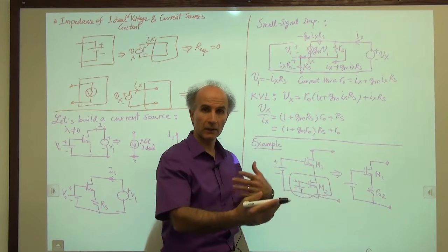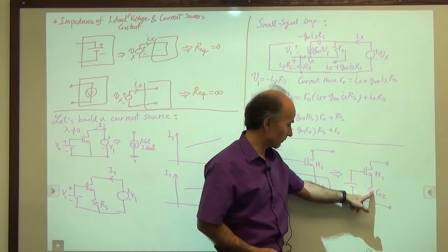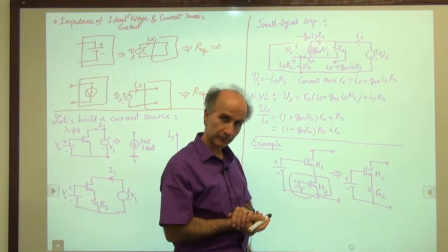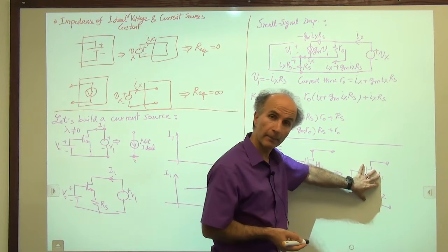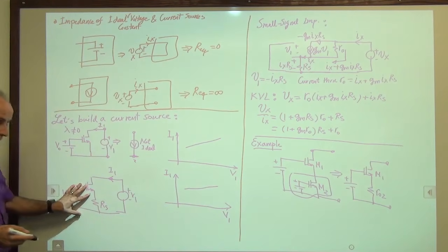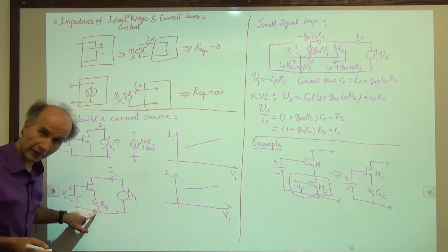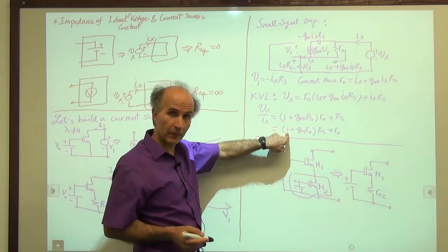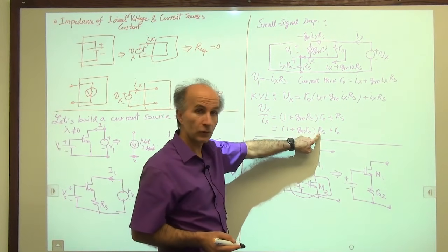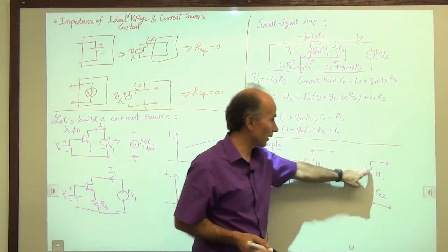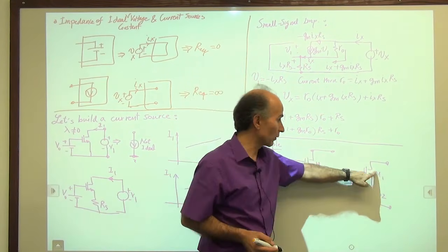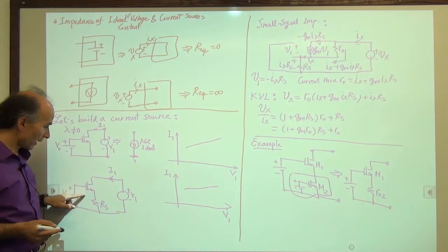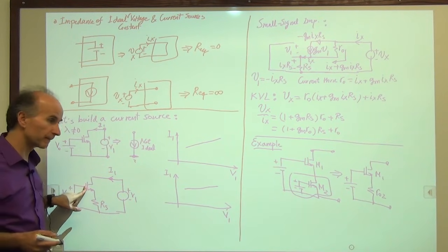Again, I'm mixing small signal and the schematics together. This is small signal, this is schematics, and so forth, bias conditions, all that. But don't worry about it, it's okay. So now this circuit maps to this circuit. The only thing that we have called RS is RO2. So the result that we obtained before is readily applicable. We just need to change RS to RO2, RO to RO1, and gm to gm1, because gmRO belonged to the original current source transistor.